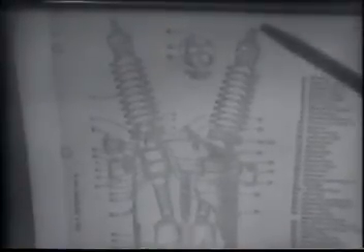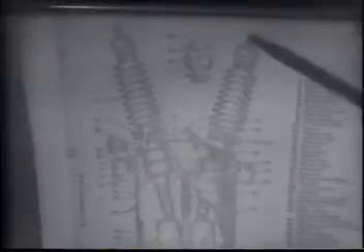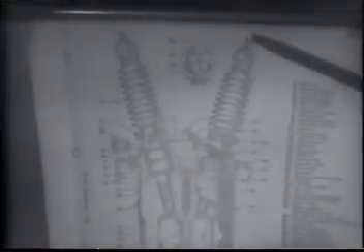And these paper cylinders are sized so that you maintain the same voltage across each cylinder. This is what's called a capacitor or condenser type of bushing. And on the outside of this, we have the porcelain protection from weather and also from voltage flashover from the power or the line terminals to the grounded case.